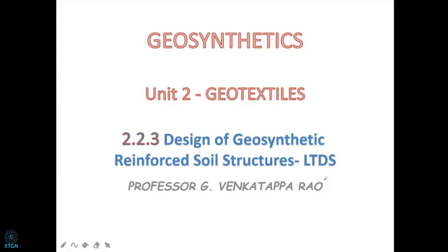So in trying to do this, going back to the first sketch I showed you in the beginning, we are worried about the friction. Friction we'll talk more about probably when we start geogrids, how to find out the frictional coefficient in terms of the pull-out method. Also by the modified axial, we'll go into details when we start the lectures on geogrids. So the second and most important point is how to get the design strength of the material.